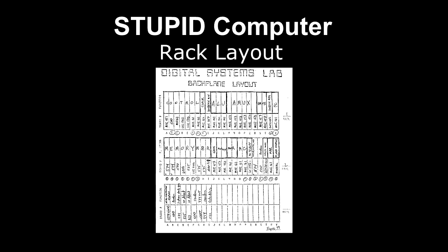And in most cases, they're called MSI and then a number. If you replace the MSI with 74, that's what it had on it, although it might have more than one of them. There's an LSI. Well, the memory is an LSI 2102. That's the 1K by 4 memory. And I think there was some small scale. Well, the small scale integration are the 500 series there, I think. I see 574, which would be most likely 7474s. There might have been more than one of them. 500 was probably NAND gates, 7400s. Yeah. And then LSI 1702s.